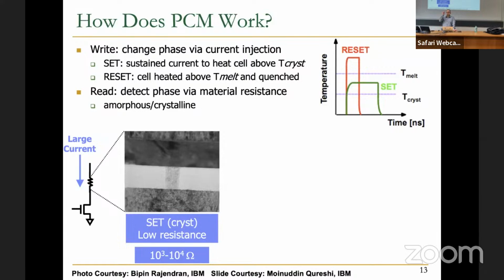Like how expensive? Yeah, I cannot say it's cheap. It's expensive, of course. But similar to DRAM, the overhead can be amortized when you design a main memory, because you are sharing that circuitry across the whole array, for example. If you want to have many small emerging memory technologies and put all this sensing circuitry in each of them, then yes, the overhead might actually be huge, right?